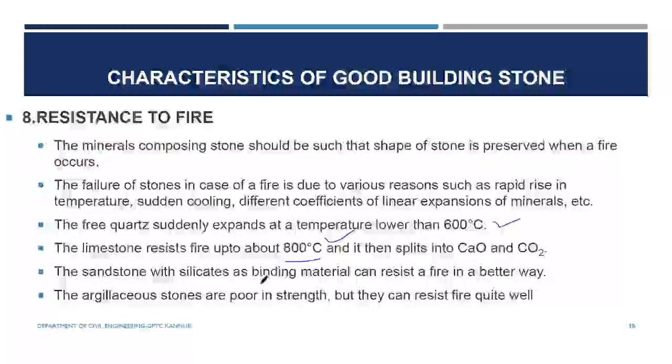Sandstone with silicates as binding material can resist fire in a better way. Sandstone is a good material. The argillaceous stones are poor in strength, but they can resist fire quite well. So it's a fire resistant material. Argillaceous stones are fire resistant materials. That is the point that you have to remember.